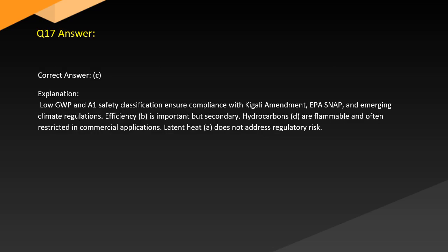Answer. Correct answer: C. Explanation. Safety classification ensures compliance with the Kigali Amendment, EPA SNAP, and emerging climate regulations. Efficiency, B, is important but secondary. Hydrocarbons, D, are flammable and often restricted in commercial applications. Latent heat, A, does not address regulatory risk.